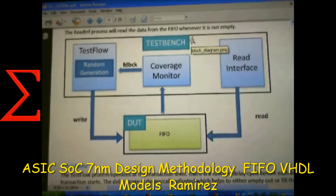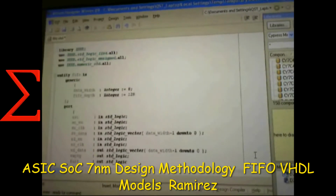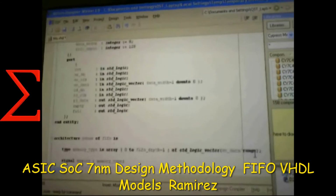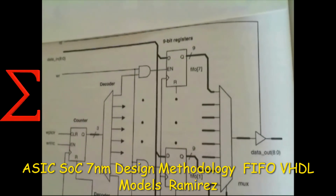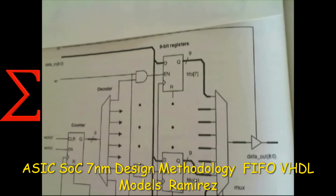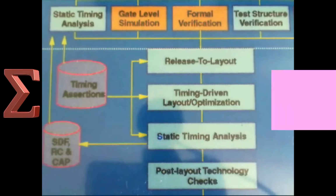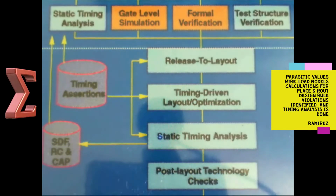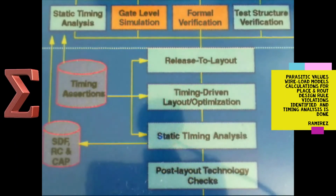Defining the design environment by specifying operating conditions, specifying wire load models and system interface characteristics. Operating conditions include temperature, voltage, and process variations. On the other hand, the wire load models estimate the effect of wire length on design performance.